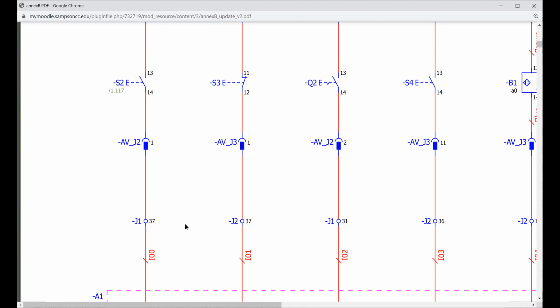Exactly. That's how we go to the button and how we go back to the PLC. He's identifying everything. You have to have the power going to the button, and to have the return to make it back. Whenever everything is good and you press it, you have power here to make it go into the internal PLC.